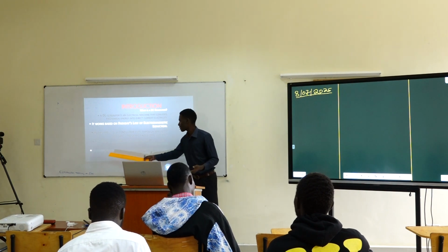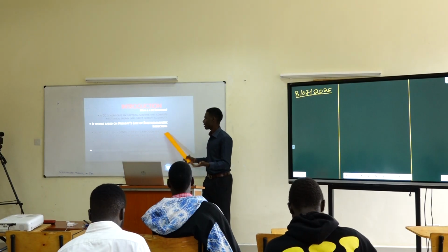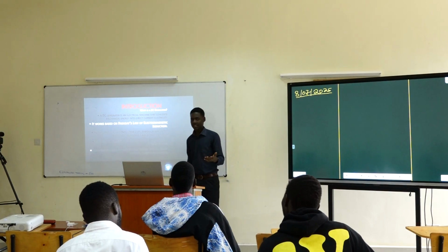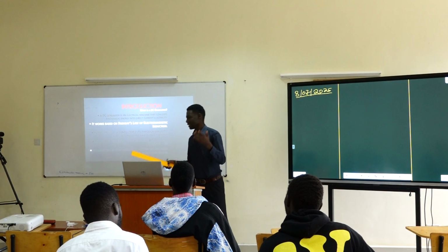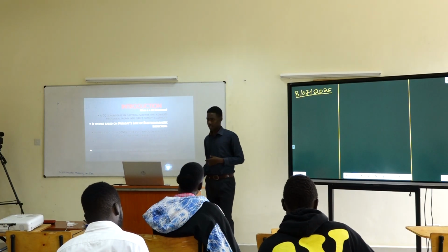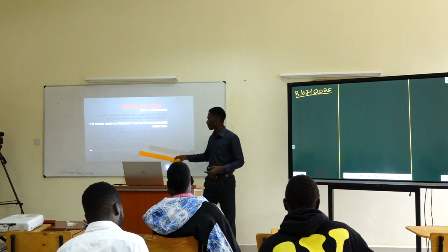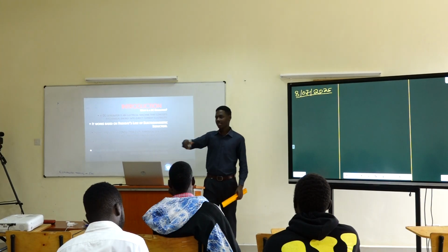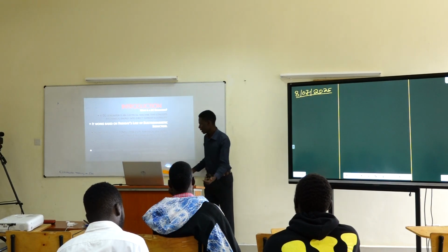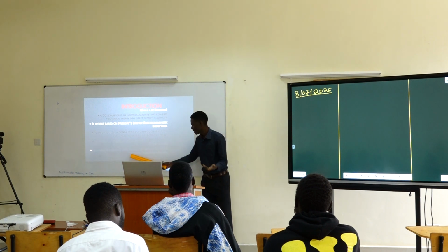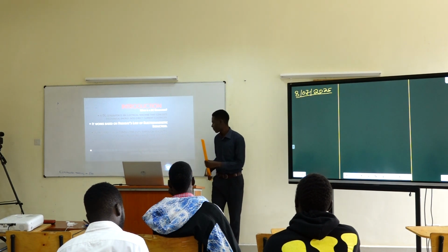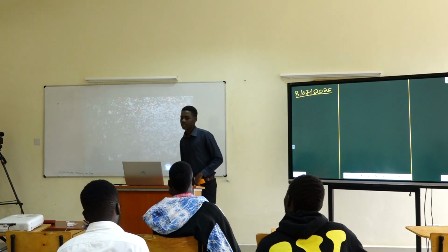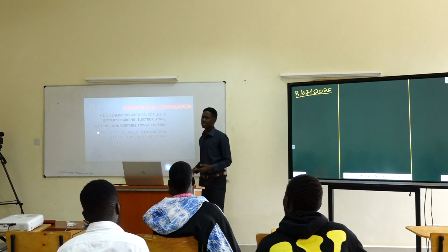So you have to understand that a DC generator works based on Faraday's law of electromagnetic induction. In the process, a conductor cuts through the magnetic field lines, inducing an electric current. The output current is unidirectional, or DC, unlike in AC generators. Common sources of the mechanical energy that we use to rotate the conductor in the magnetic field include diesel engines, turbines, and cranks. So, we still continue and look more at the DC generators.